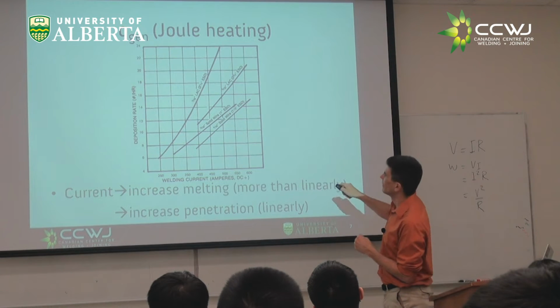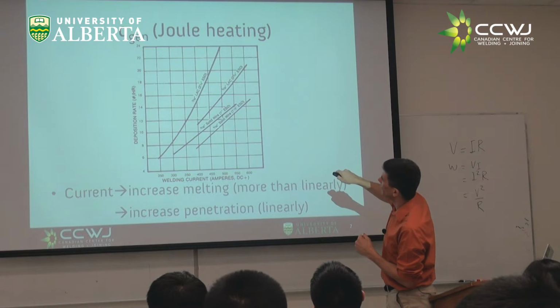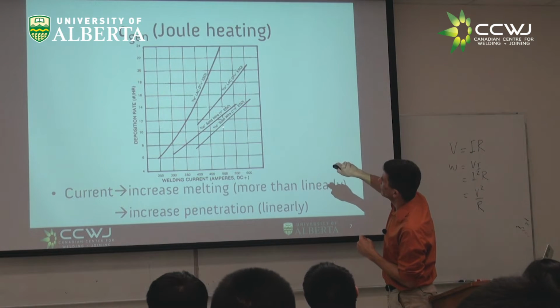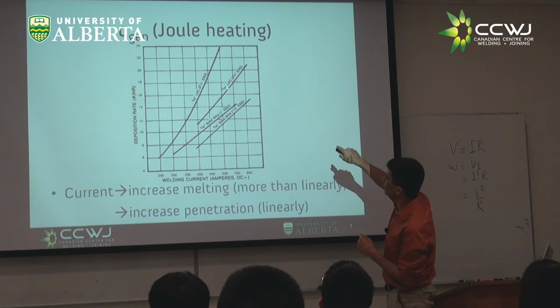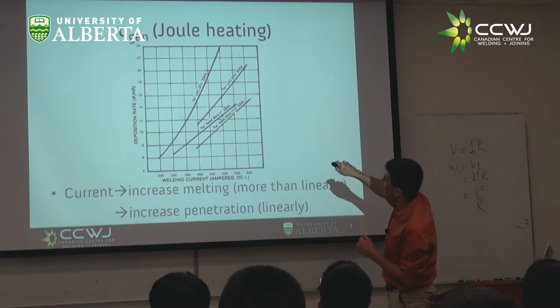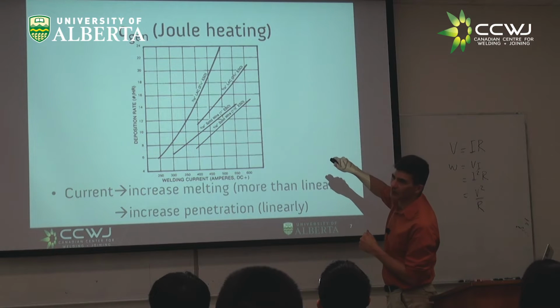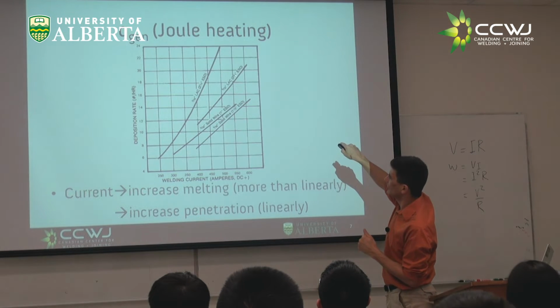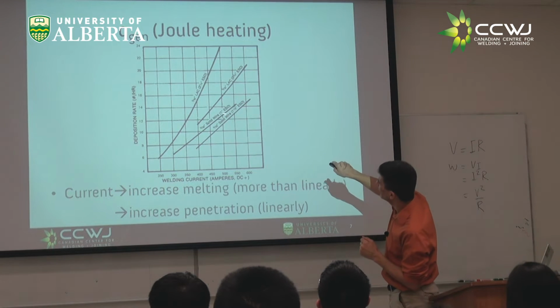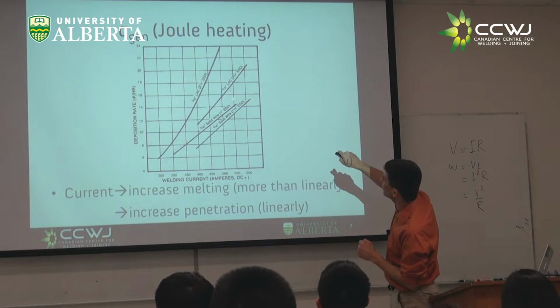Okay, check it out. Here they have this, let's compare this. 532 wire, this is for submerged arc welding. 532 wire here, 532 wire here. This has 1.5 inch stick out. Here you have 2 3/4 stick out. It's longer, and you see the deposition rate in pounds an hour went up.